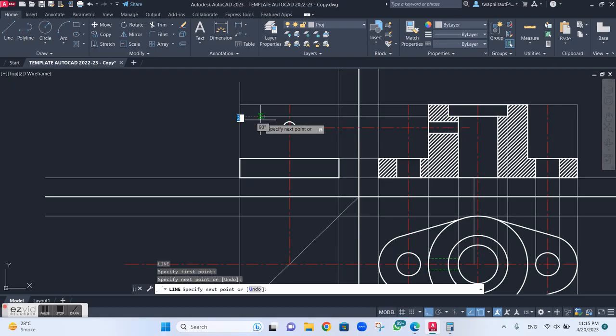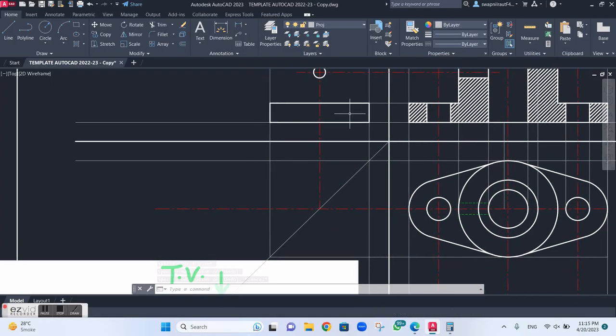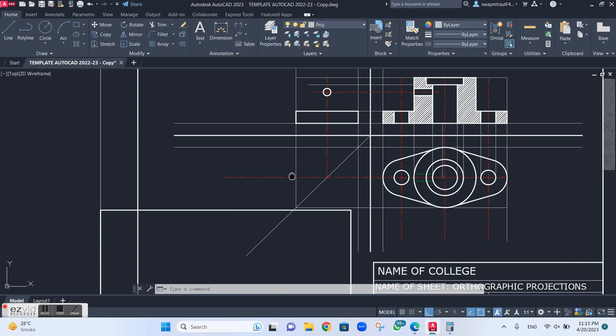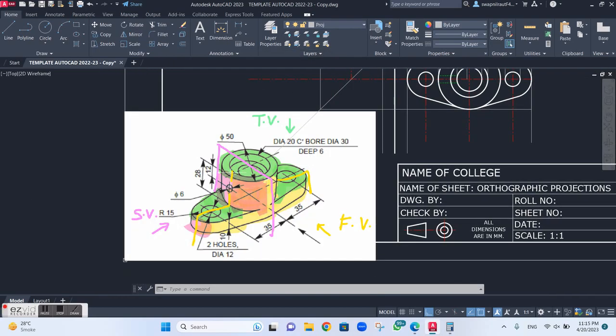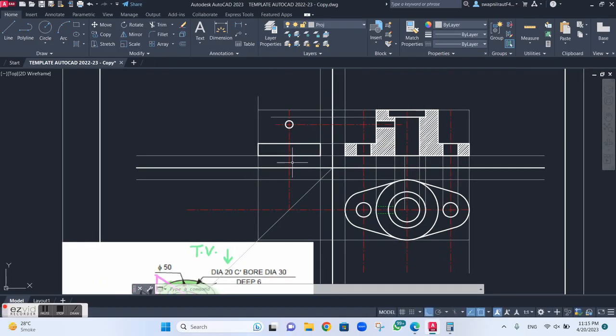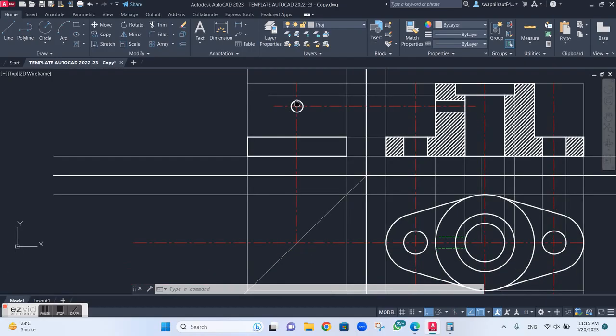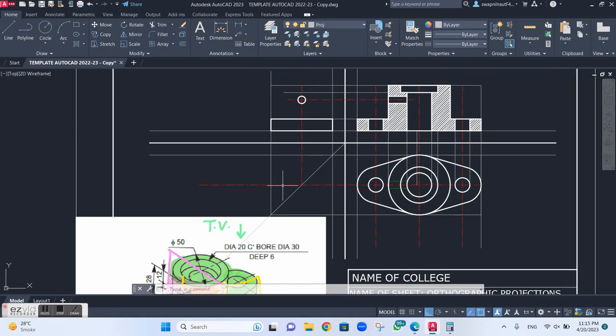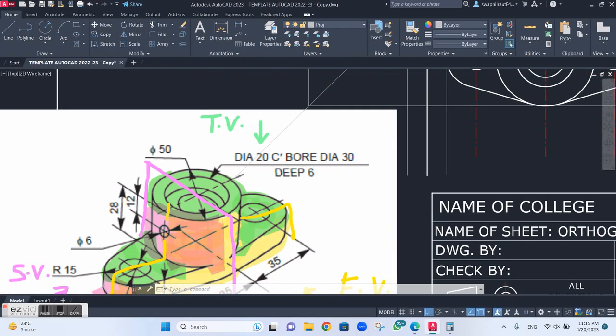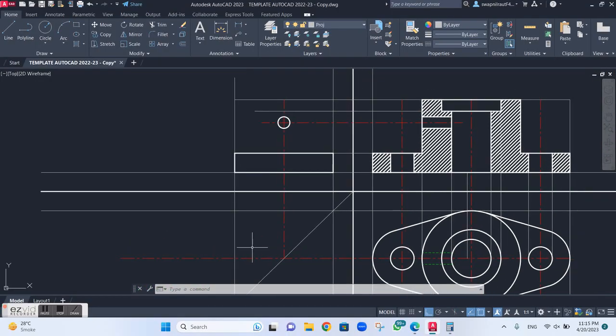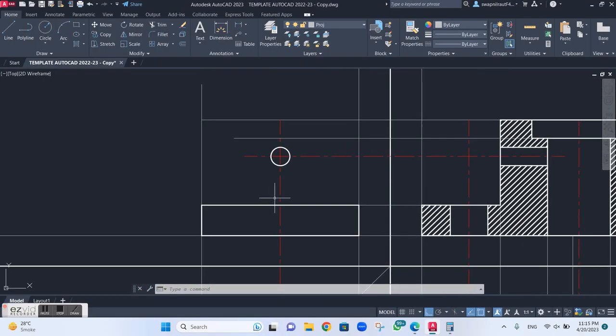Again, since it is a circular body, in the front view and in the side view a rectangle will appear. So I've taken the projection from there. Again these are inner circles and not visible, so those will be hidden. That counterbore hole will also be hidden.